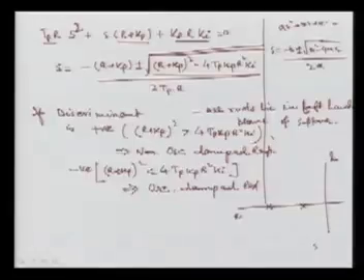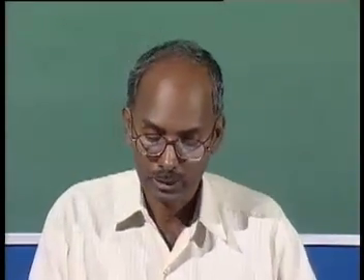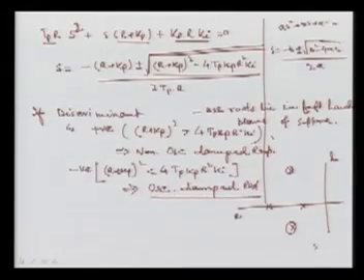But if it is negative, we get the roots here and here, and then it will be oscillatory. We have imaginary terms, so we will have an oscillation frequency, decided by how much negative we have, and our response will be oscillatory. So this is called an oscillatory damped response.